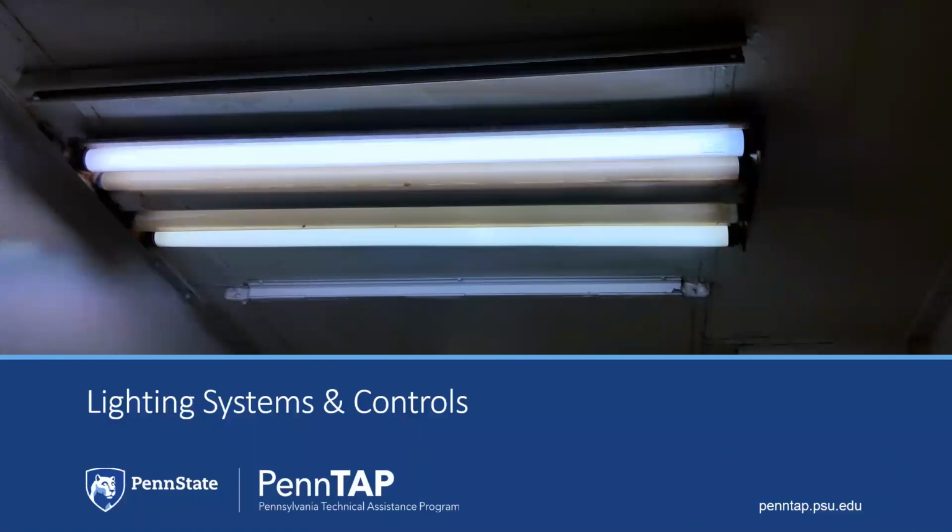Things to look for. Does any of your lighting have any controls? Are they just manual switches? Do you have dimmers? Do you have clocks? Are the proper light levels being maintained, or are you overlit? If you're overlit, is there an opportunity to delamp? Using a light meter, you can verify the light levels to see if you are meeting the Illuminating Engineering Society's recommendations for light levels in specific spaces.